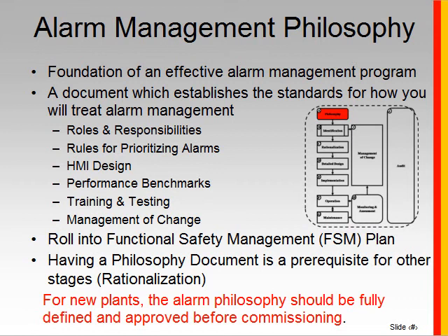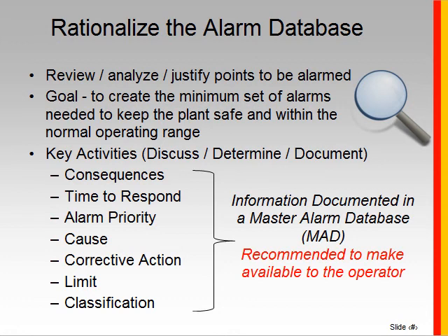And many folks that are starting to see this alignment between the safety and alarm management life cycle have started to think about rolling their alarm management philosophy into their functional safety management plan, which is a great idea. Now, having this philosophy document done and in place is a prerequisite before you can execute other tasks in the alarm management life cycle, such as rationalization, which is what we're going to talk about next.